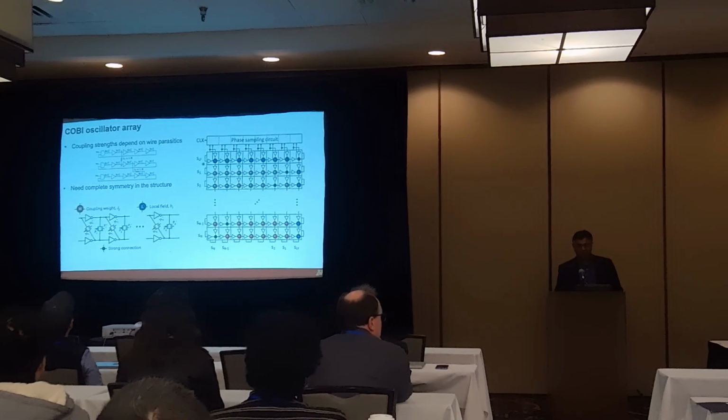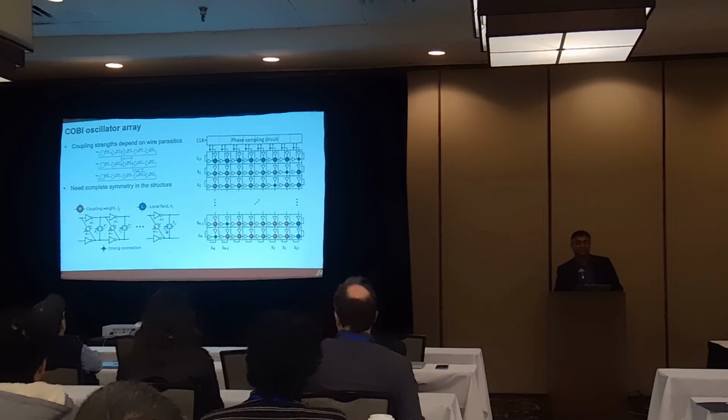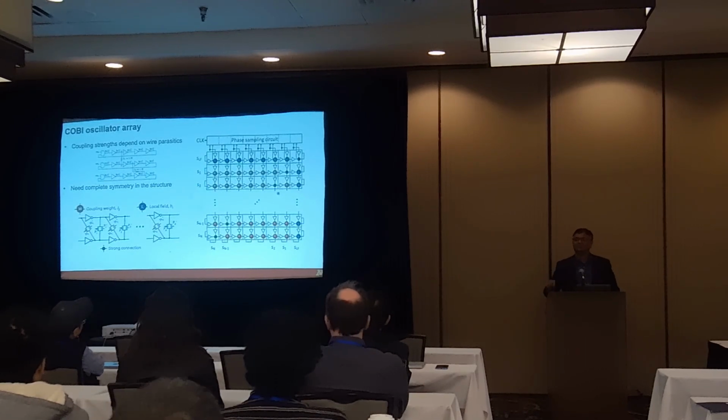In fact, even the topology of the structure turns out to be these coupled ring oscillators, some in this direction, some in the opposite vertical direction. The coupling goes through transmission gates in this particular version, and the transmission gates basically emulate the resistors, and you can actually show that using this you get extremely high symmetry. The layout guys were very, very fussy about this, so everything had to be perfectly matched.